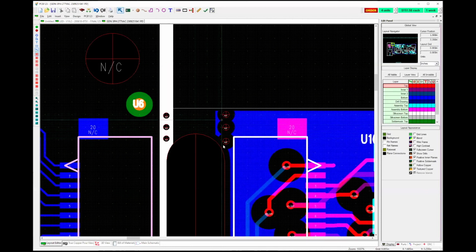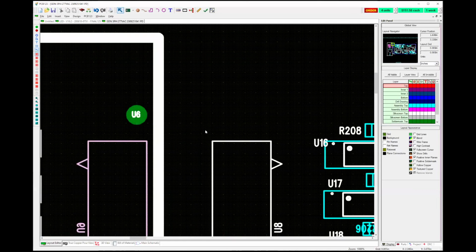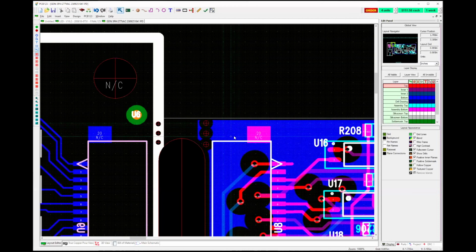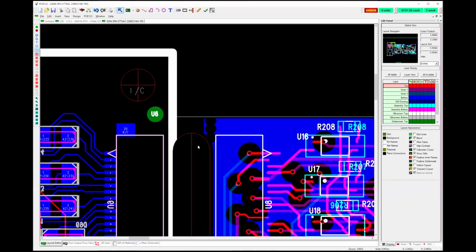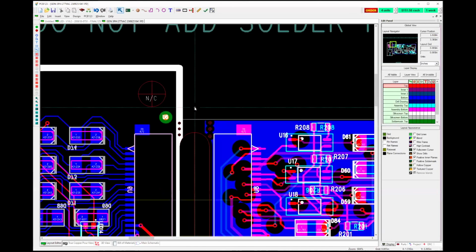What you risk by having something like this is if I was going to just snap this off now, and I had a surface mount component right here that was fragile, like a ceramic capacitor or a diode, something along those lines, and too close to this. When I go to snap it off, the board bends a little bit. You can crack those parts, but the truth is it's that easy to put those in.